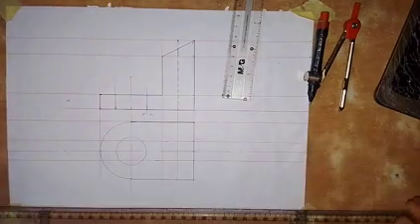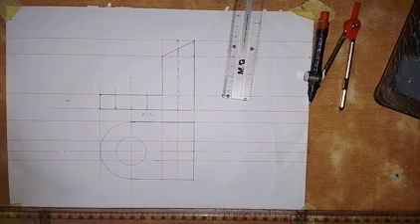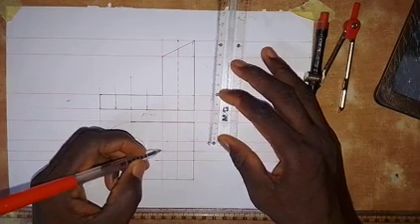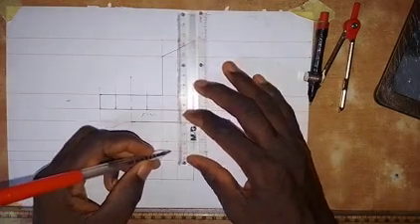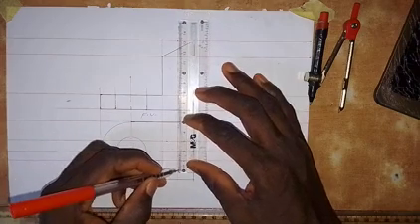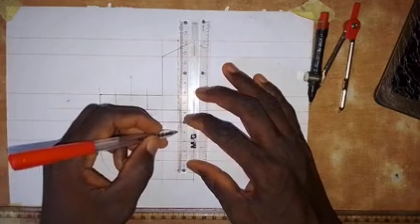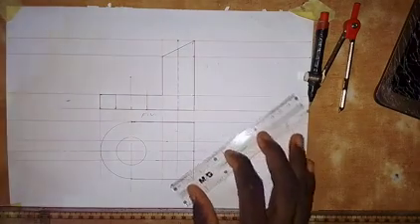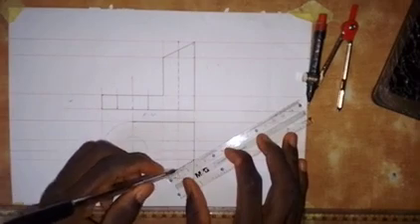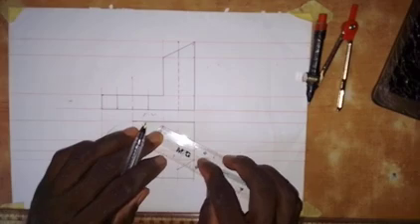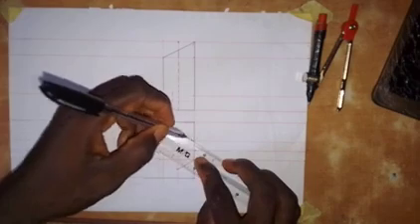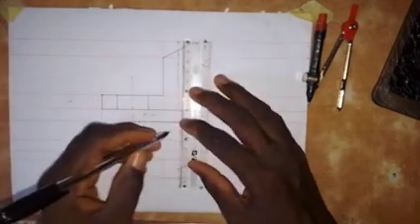Having drawn the horizontal line, the next thing that we are going to do, from the center line along this part here, is take 20 millimeters down for us to draw the shape. So 20 millimeters down and 20 millimeters up. Now we join this point with this, and this point also. We join these 2 points together like this, and then we make this line a thick line.